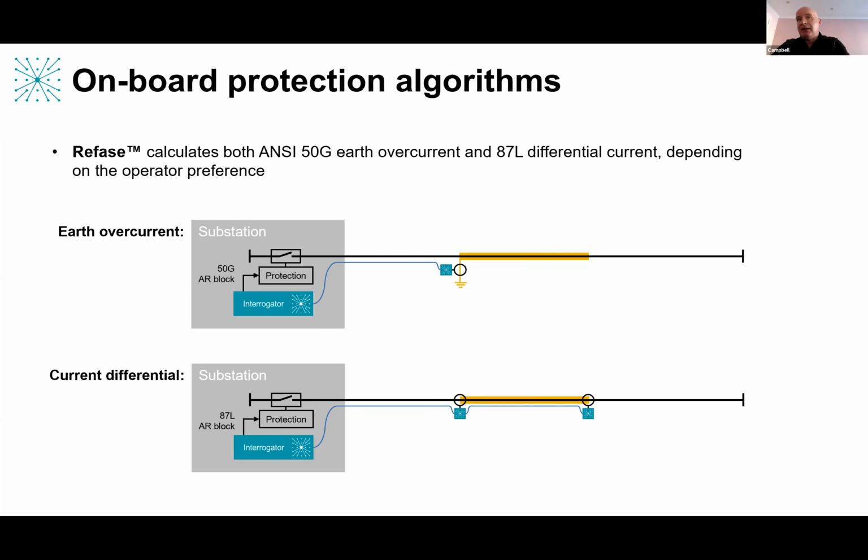I think my take on that, Phil, would be it really just depends on the nature of the installation itself and the type of fault that you have. Differential current will capture every type of fault, phase to phase, phase to earth, and so on. Clearly the earth overcurrent protection will only catch a fault if that actually involves earth itself. So you'll catch the vast majority with that.